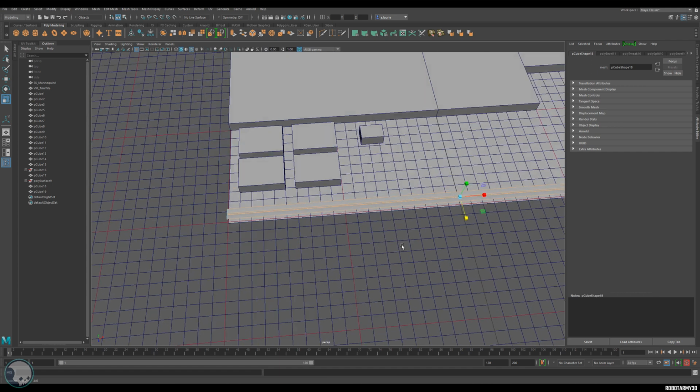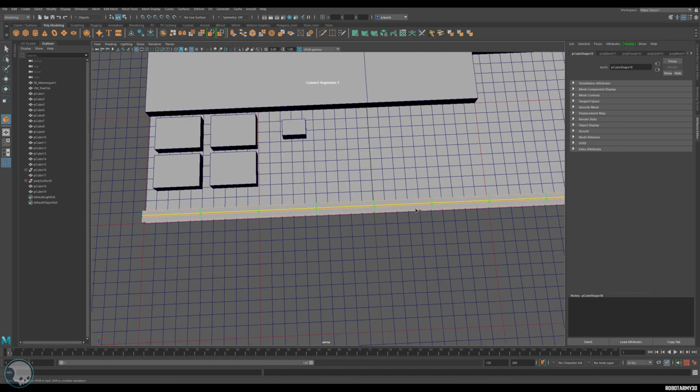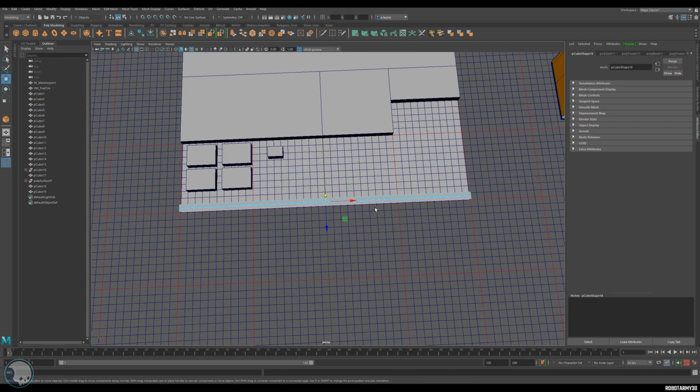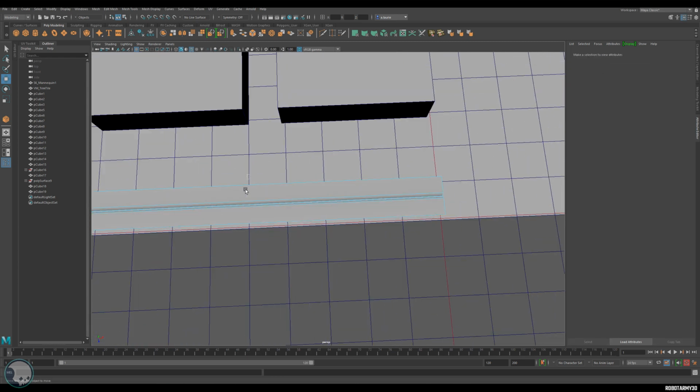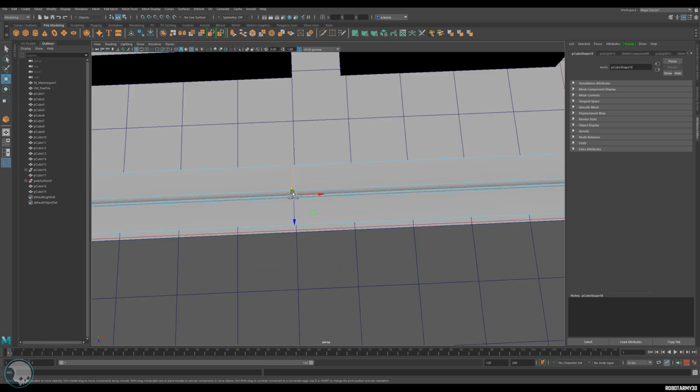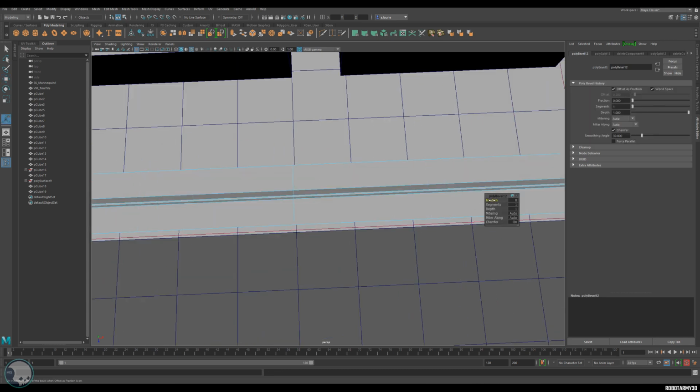So what I'm going to do is grab these edges, connect, so I'm going to split it in half, edge, connect, and half again, and then I'm going to put a connection in here and then bevel that just to a tiny amount. Now remember, when you're using the fraction, if you just grab it, it'll move quite fast, but if you want to slow that down, you can hold Control to make a much slower movement. You also have this here which changes the movement speed. You just click that little icon to change how fast the numbers scroll up.